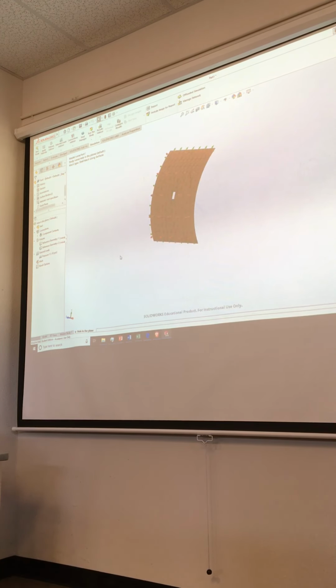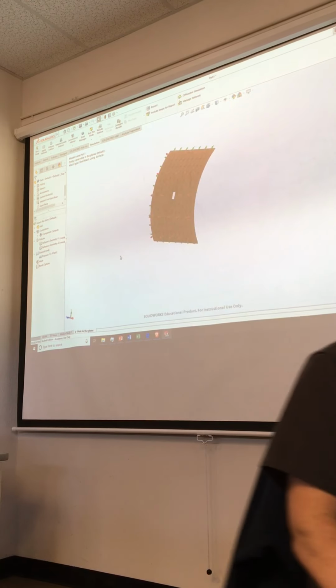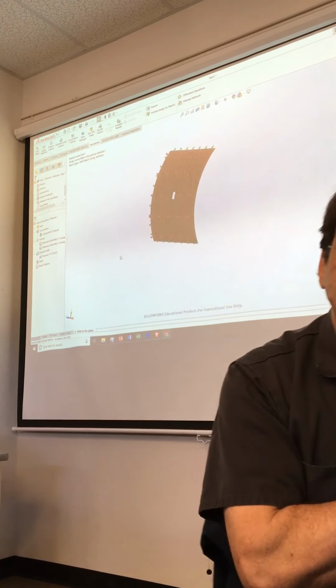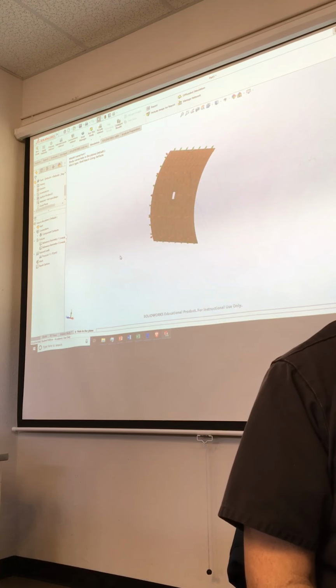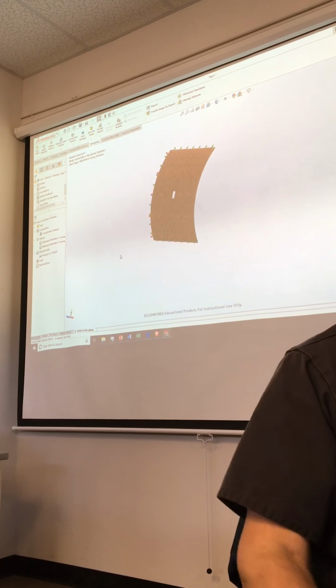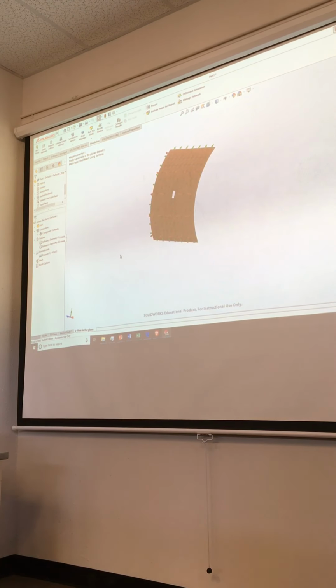Now, are we happy with it? You gotta do that force thing. Gotta do the force, right? So how big's the force? Calculate it. Oh, we gotta calculate it. So what is it? I have, let's see, I got 10 PSI. What is it? P times A, right?